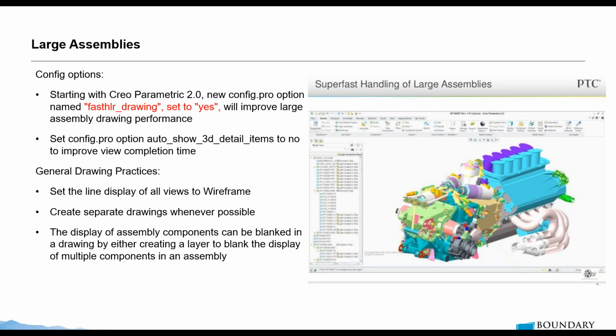It sounds like there's a lot of work in there, but if your templates and formats and your config settings are properly set up, that whole thing is just a breeze. You just open up the correct template with the correct format. All the basic information is already there. If there's standard notes and things like that, that's already there. You don't have to go and redo that. You can copy from other drawings if you need to. So you can work through that process a lot quicker.